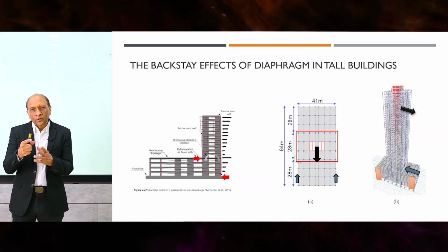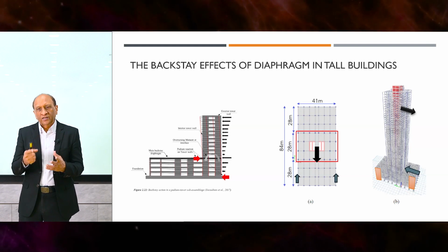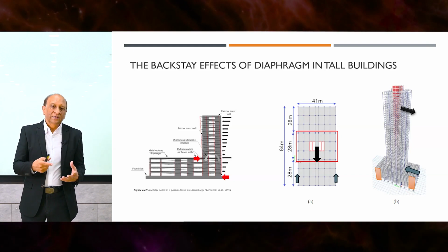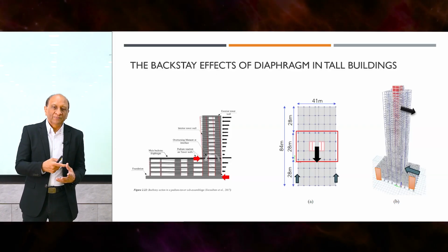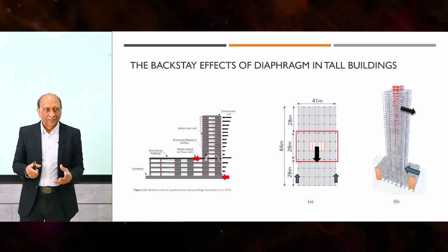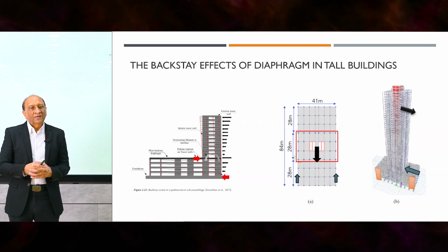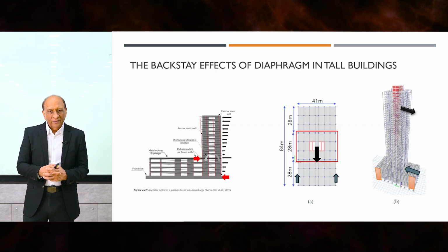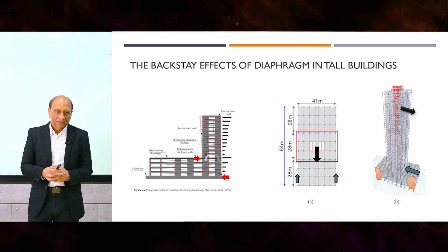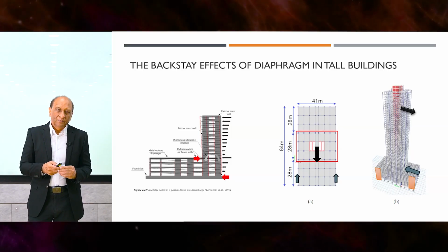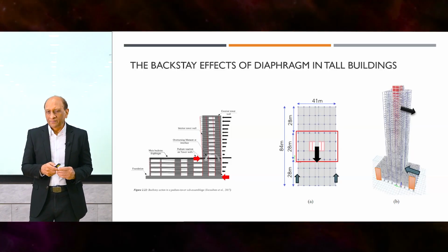And so before the load, the shear, can transfer from the wall to the foundation, the podium floors will intercept it and try to spread it around. And that's where the large force transfer will occur in the floor diaphragms, especially in the podiums or even in the basements. And this is complicated stuff, and many methods have been developed to do that.